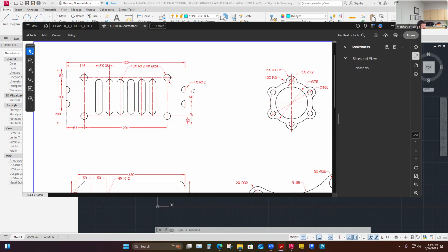So I look at this and I think, can I make some corrections for clarity? Should these center lines pull through to show alignment? That's debatable. These could pull across so that I don't have to dimension over here. Or I could actually say 2 places, and that would be inferred that these are the other 2 places. Like I could do a 2x 75, 2x 50, and that would infer that these are the same. So this could be left a little bit of a gray area, as far as these locations. I'm going to use these, and that is what it is, 75 and 50. And they are at a radius of 12.